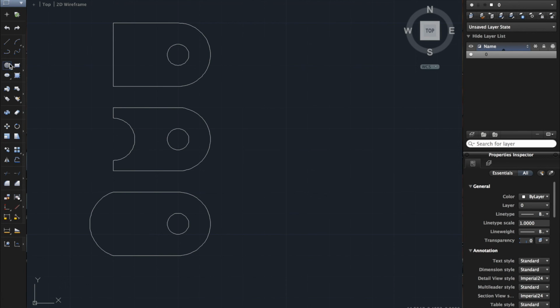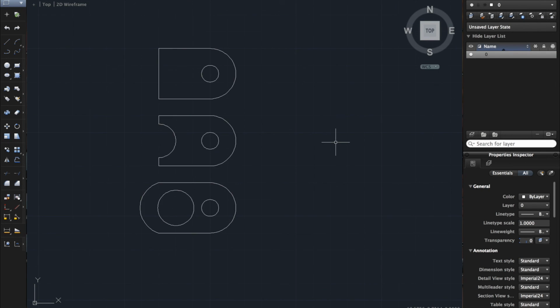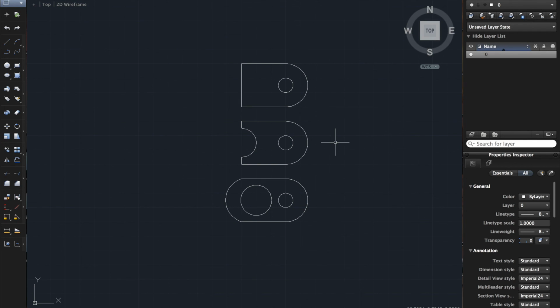If you want, it would be cool if you could put another hole here. Well, for that you'd need to do that, and then of course snap grid off, and then make your other hole. You can even do it bigger if you wanted. And you can make little mounting brackets. You can do bigger, bold, smaller, whatever. There's a whole bunch of stuff you can do with that. And it's just to give you guys an idea of things you can do with AutoCAD.